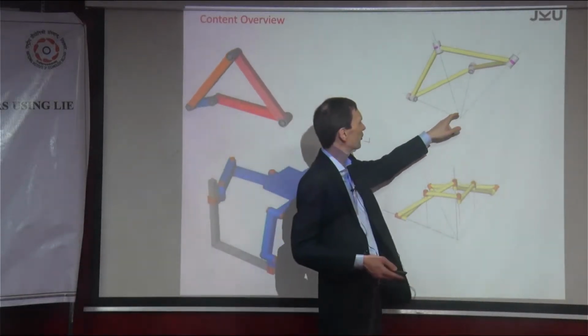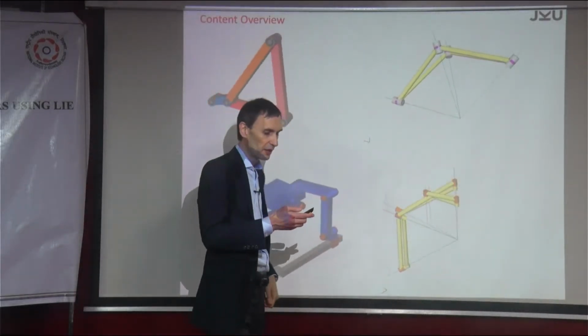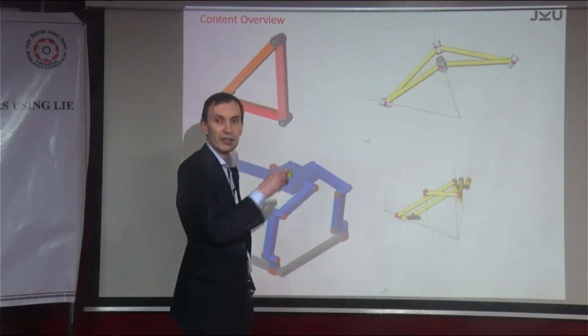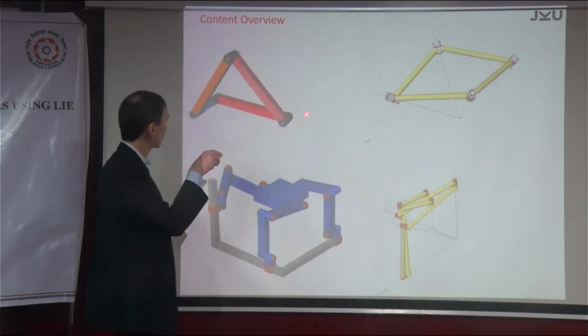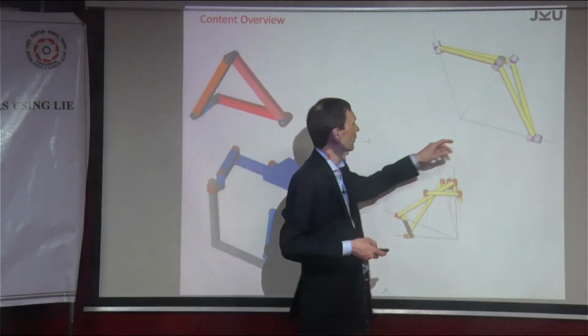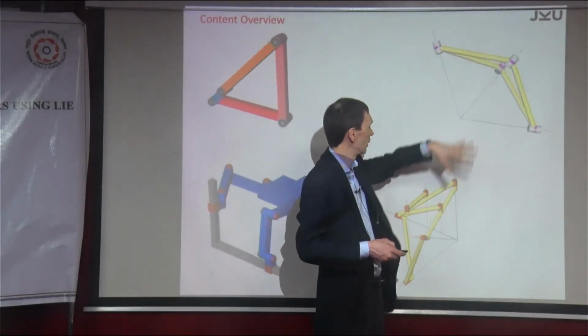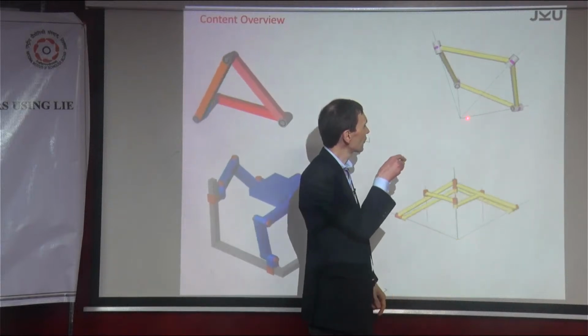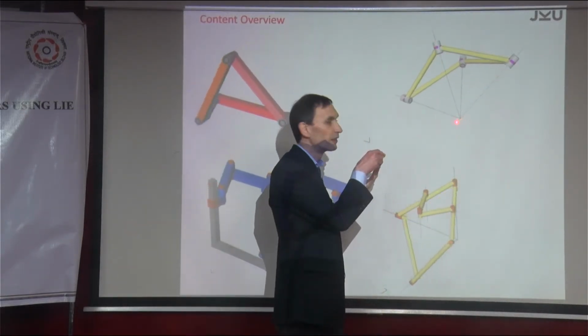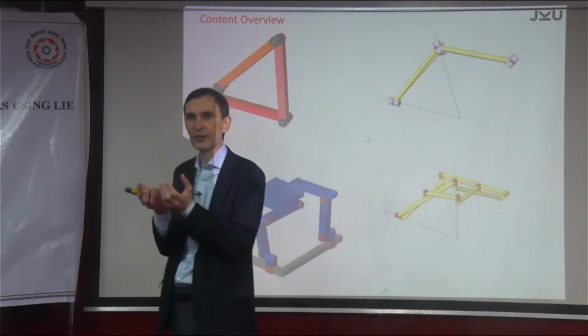What's the degree of freedom of that system? I hope you understand what it says here. This is a revolute joint. We have 4 revolute joints, okay? Here we have 4 revolute joints. And there is an intersection. For this special mechanism, the axes of the 4 revolute joints are intersecting permanently. Okay, this is why it's called a spherical mechanism.